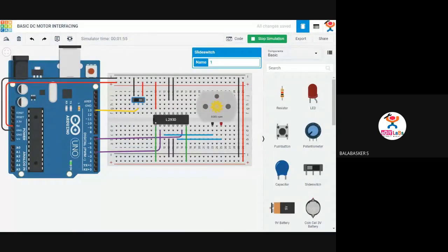For your reference, again I have shared the things which I promised to teach. First we learned about Arduino and robotics, and next I taught you how to control a single LED and multiple LEDs with RGB. Then we interfaced buttons and checked the output. Next, we added a potentiometer and varied its value from 0 to 1023, and controlled an LED based on whether the value was below or above a condition. After that, by using the analogWrite function, we controlled the PWM pin, like brightness control. In that also, we connected a DC motor and checked with the pin.